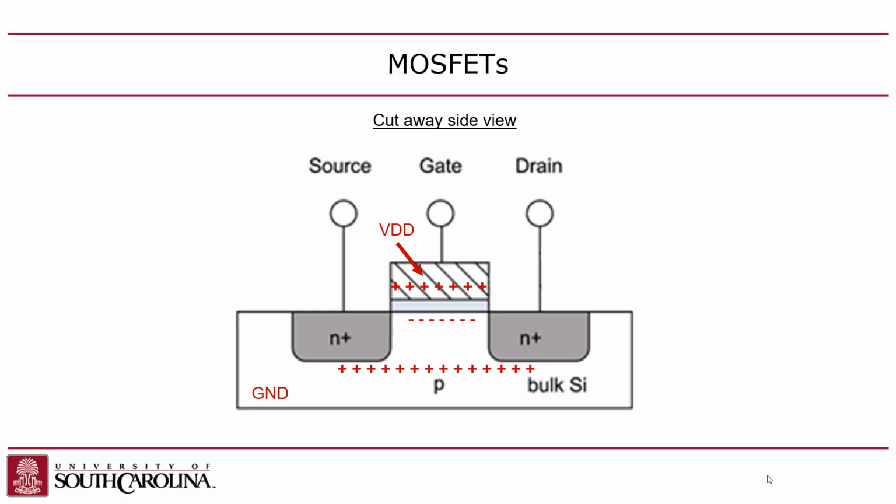Right? Does that make sense? So those minority carriers are always there, but they're real hard to find unless you get them up in there. Now, what ends up happening is really interesting, because when this happens, the channel, even though it's part of the substrate, actually becomes disengaged, disconnected from the rest of the bulk, the substrate.